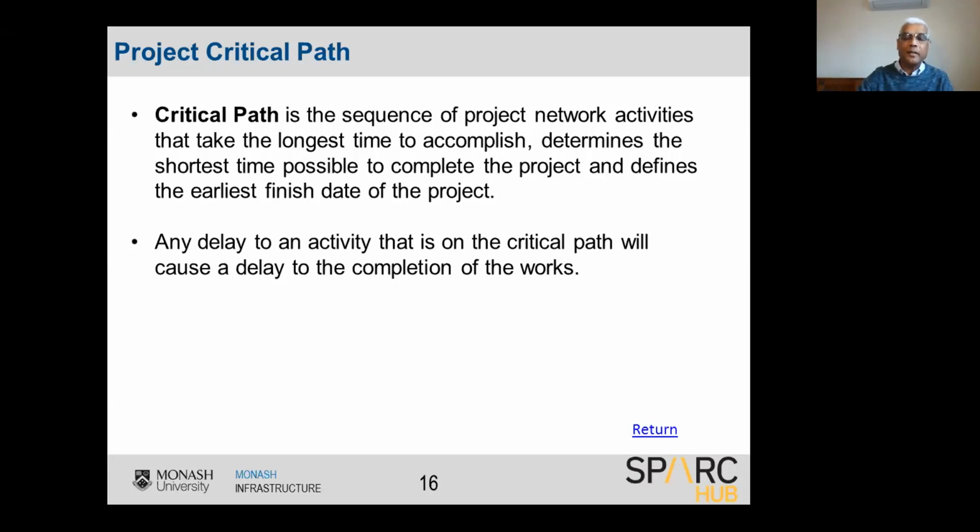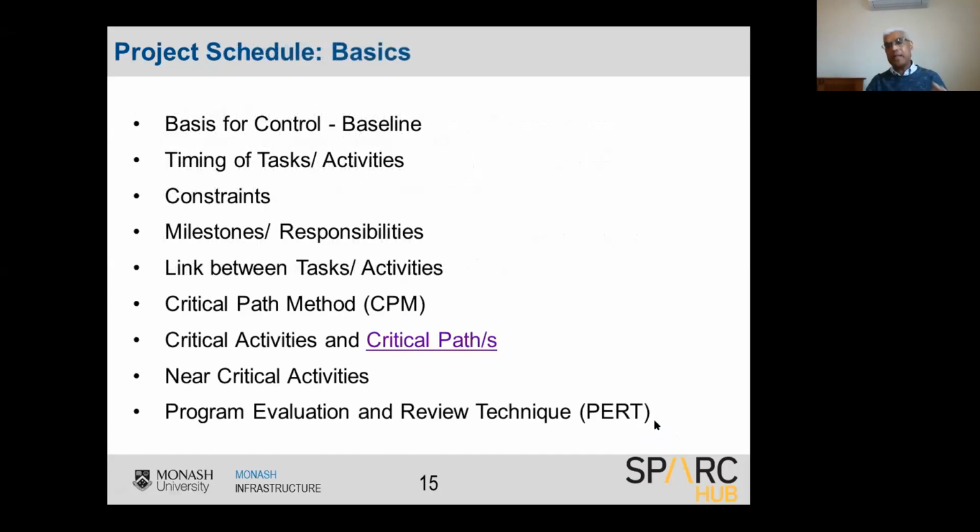However, if the critical path is the factory work and there's a problem in the factory due to some resource problem or other aspects, then that will delay the project. That's why the critical path is very important, because any delay to the critical path will delay the project. So that is a very essential consideration when you prepare schedules.